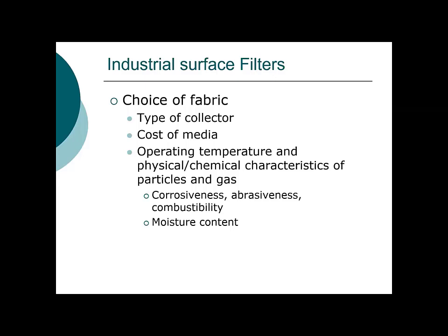You can imagine it's very different in terms of the type of material that you would use for creating a disposable furnace filter versus the type of material that you would be using in these very large baghouse filters, where the fabric that's used is reused for a significant period of time, up to 5 or so years. Longer if it's ceramic, though.